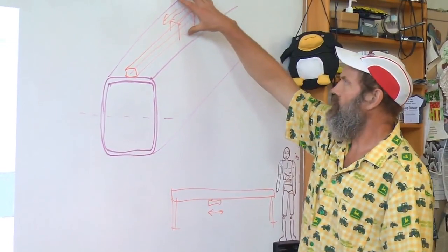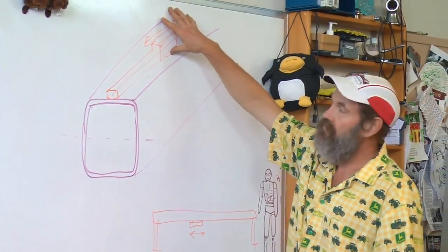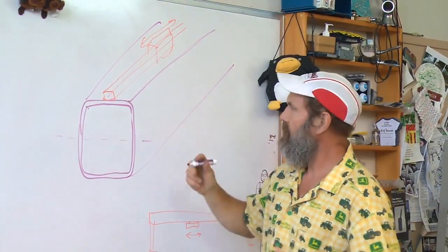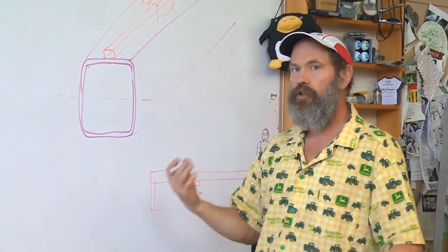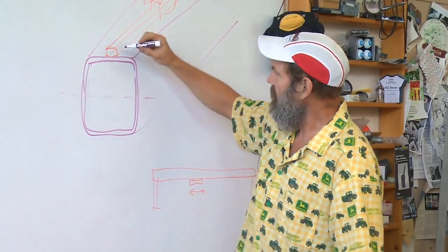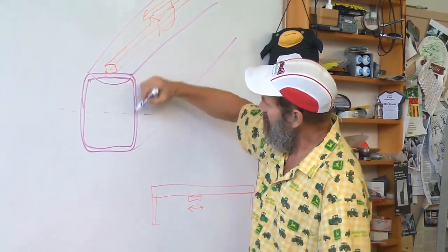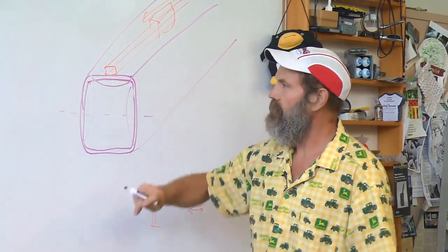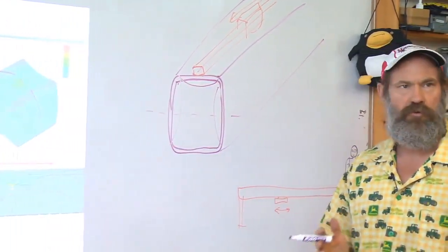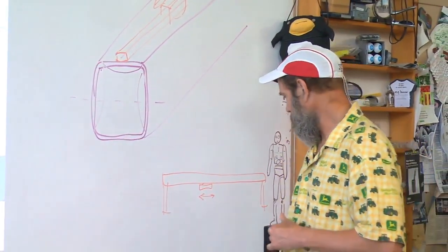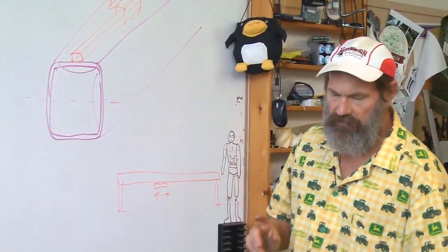If I have high loads on this carriage, remember, imagine your whole structure is made of rubber. And I load it and watch what happens. This structure can bend in, like shown here. So how would I do a first order estimate of what's happening? Now this is where finite element analysis is also very good as you're a designer and working in areas that you may not be familiar with and don't understand how to model.